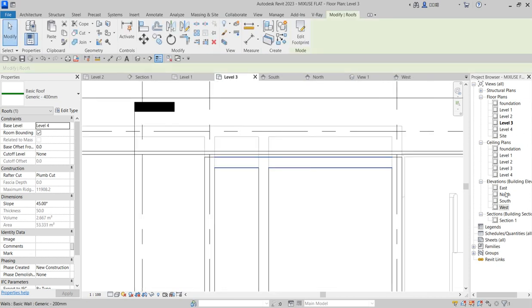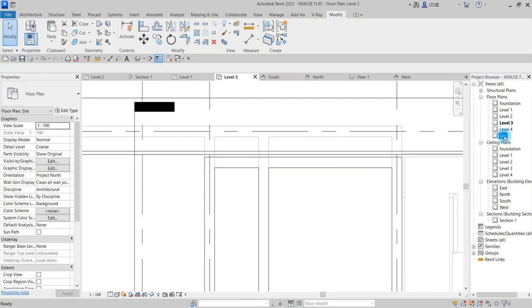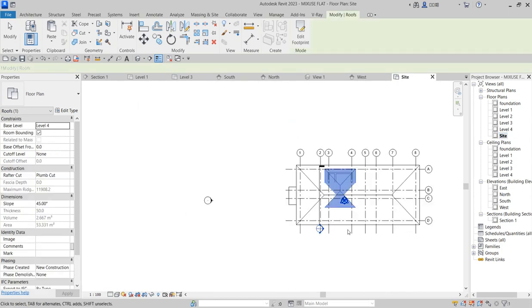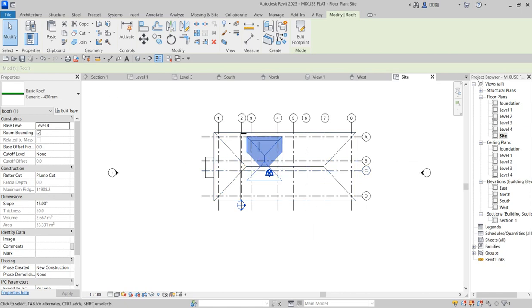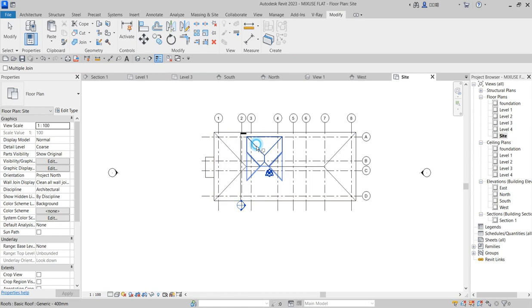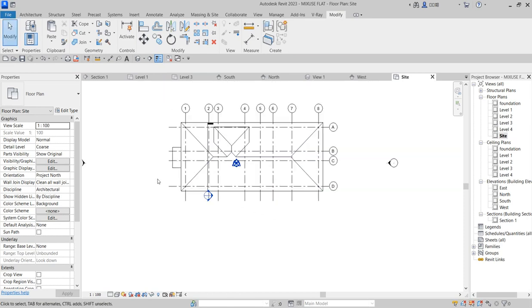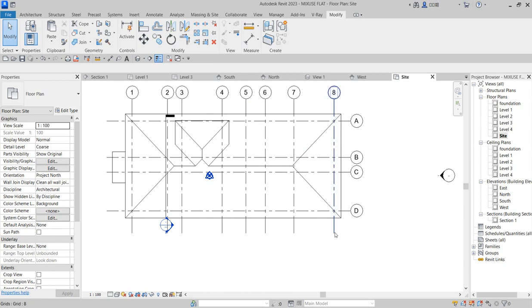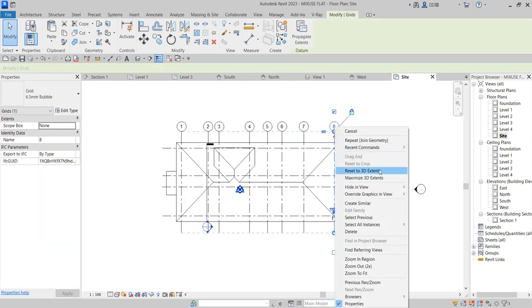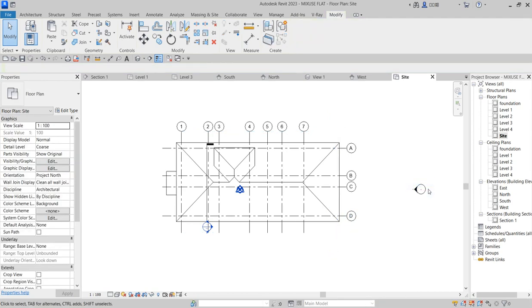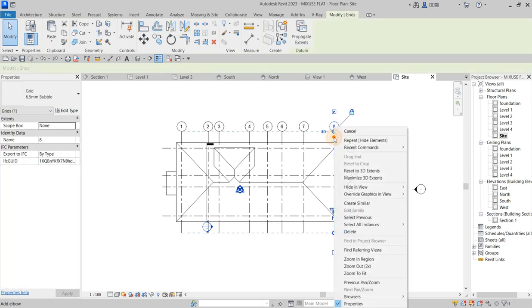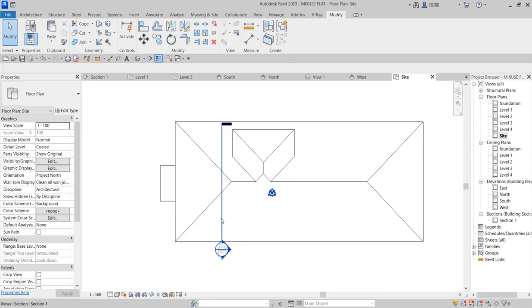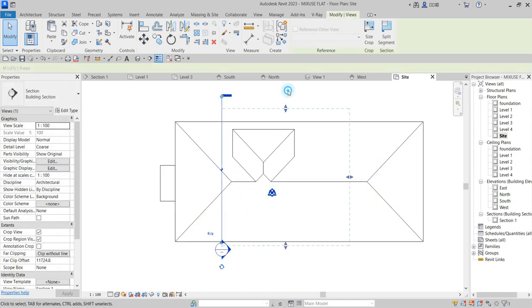So no attachment. Then you go to your site plan to fill the whole thing in order. You are seeing this double group in place. That does not matter. All you need is to click on join here and join them together, so they become a single group. So anytime you hide this, they will be hidden. So Ctrl Z. So you hide everything under one category. Select and hide category. So they will all go, and you have that autonomy of view to yourself.